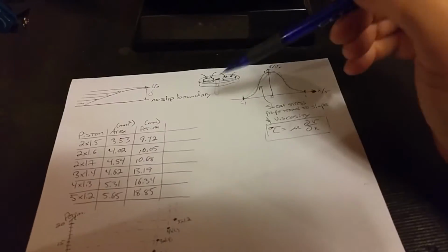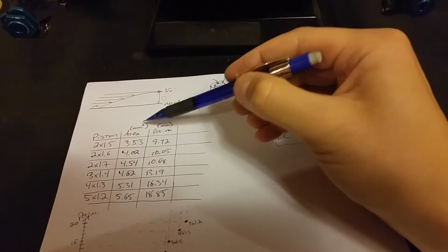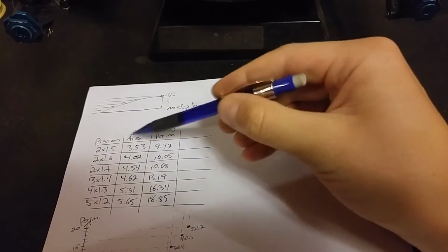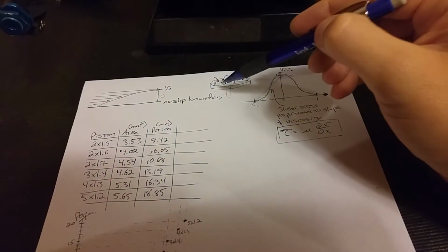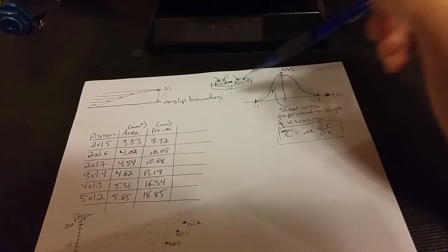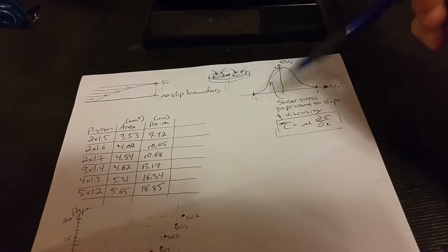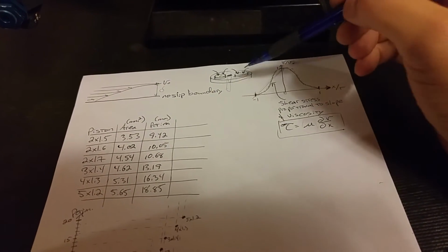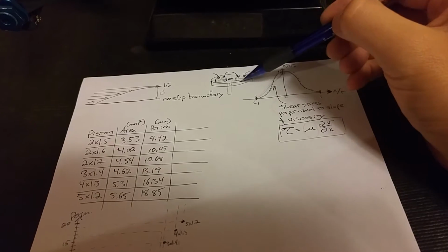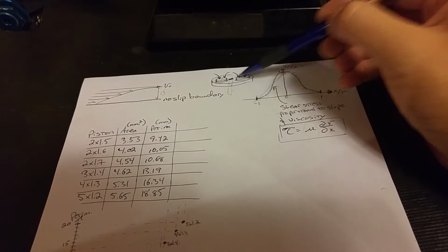So we can very broadly say that low-speed damping depends on the total area that you have in your shock piston openings, and the high-speed damping, your pack, depends on the total perimeter of all of your shock piston holes.